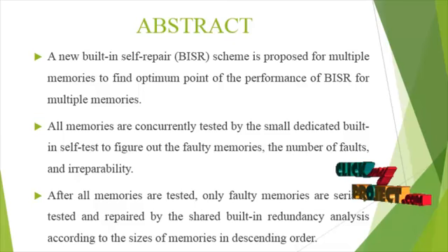Redundant spare rows and spare columns are often included in the memory. This impacts the performance and area of the memory. The memory is repaired during testing by storing faulty addresses in registers. These addresses can be streamed out after test completion. The application can be started immediately after the memory BIST process. The redundancy logic calculation will not increase the test time of the memory BIST.